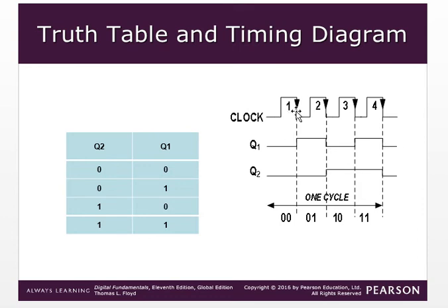What is the input frequency now? How many pulses are there? Four pulses. The first flip-flop output has only 2 pulses. It clearly shows that one flip-flop divides the frequency by 2. Assume that the input is 4 Hertz. The output of the first flip-flop will become 2 Hertz.